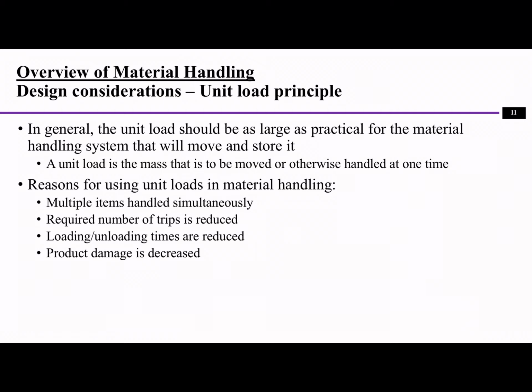So about unit load. In general, unit load should be as large as practical for the material handling system. Because when we are designing a unit load, we have to think about how often we are moving materials from one station to another, and also the size and weight of the materials. And so we can take advantage of unit load, right? We do not want to have so many trips with very, very low material amount.